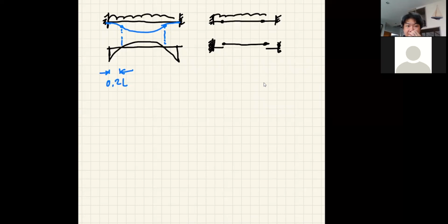So you can solve that. Okay? Because let's say, how many do you have? 1, 2, 3, 4, 5, 6 unknowns. You have 3 equations, so that's 3 degrees of redundancy. You add 2 hinges, and then you ignore your sigma Fx equal to 0. You ignore your axial force. You're fine.